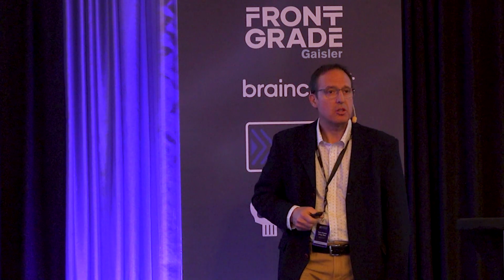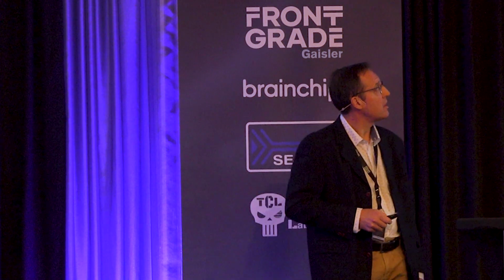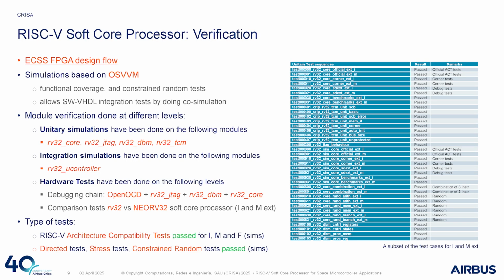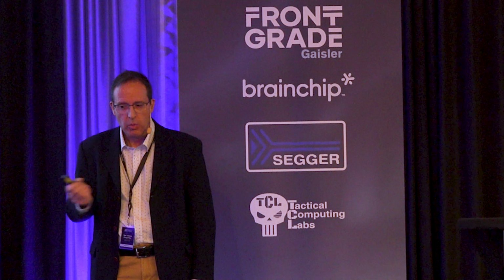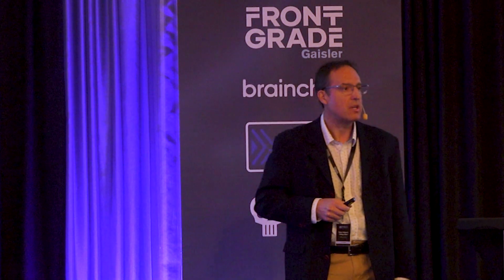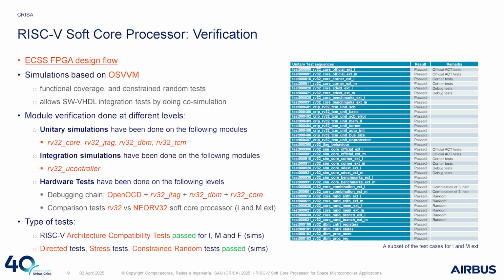Regarding the verification of the core, we have followed an ECSS FPGA design flow, the one from ESA. The simulation environment is based on the open source VHDL verification methodology, which allows us to include functional coverage, constrained random tests, and it also allows us to do software and VHDL code co-simulation, which we already prepared.